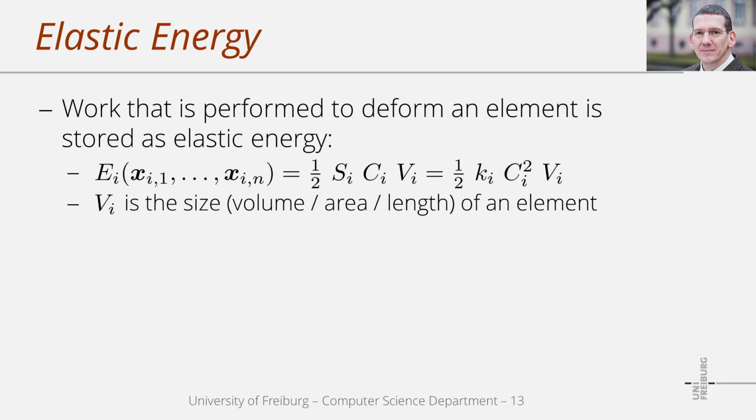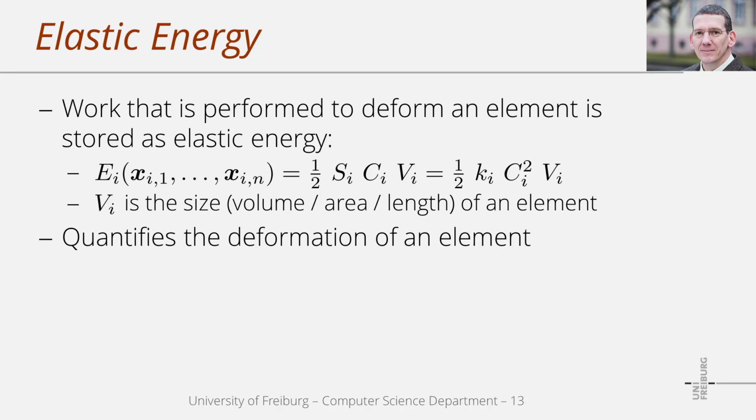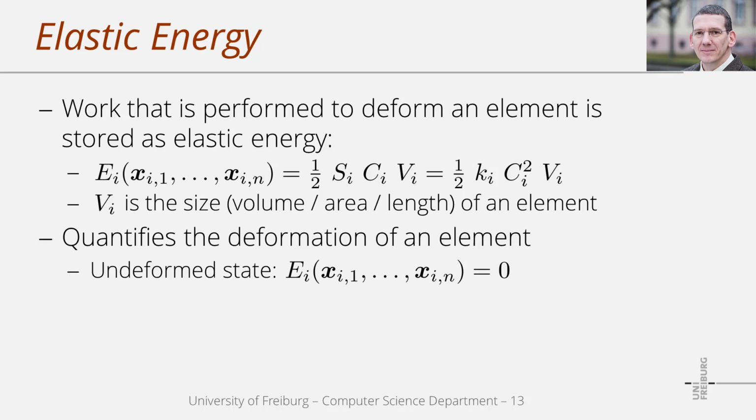As strain and stress can be computed from the particle positions, the elastic energy is also a function that depends on the particle positions. It is obvious that the elastic energy quantifies the deformation of an element. If an element is undeformed, then the elastic energy E is 0. If an element is deformed, then we get some positive value for the energy.